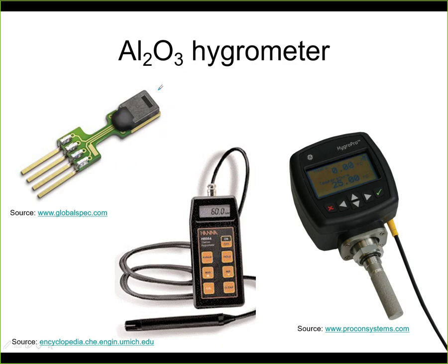This particular sensor has a digital output, so with the digital bus, in this case it's called I2C bus. In this case you can read directly the humidity as a number, and it also has a temperature sensor, so you can read the temperatures as well directly. In most applications you need to have the temperature anyway, so you can use a combined sensor like this. So this I2C bus, it's a 2-wire bus. One wire is data, one wire is clock, and the 2 other pins are the power supply voltage. So you can see that here we have 4 pins, and this is the digital sensor.